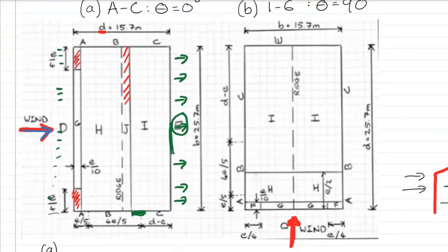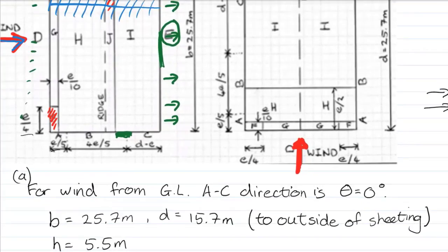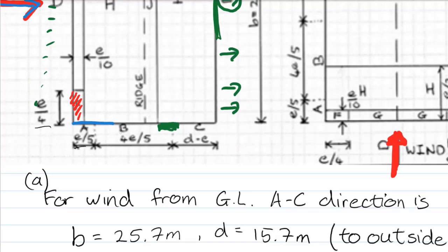And we've got to pick a portal frame to analyze somewhere within the structure. Normally the portal frame that we'll need will be somewhere in the middle of the building, because it's got a tributary area from both sides. It's getting loads from both sides of it. It is possible once in a while that the end portal frame governs, right down on the gable face, but normally it's got half the amount of load on it, so the pressures will have to be more than twice the rest of the structure for it to govern.